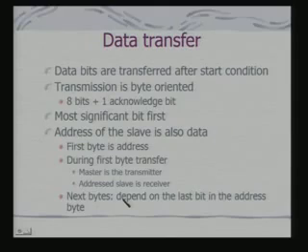So, depending on whether it is a read operation or a write operation, either the master will be transmitting the data or the slave will be transmitting the data. The recipient will always generate the acknowledge bit after transmission of 8 bits.